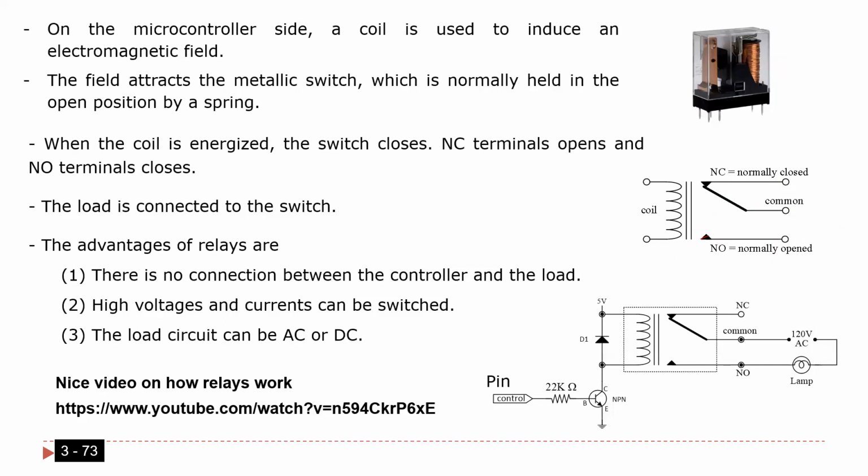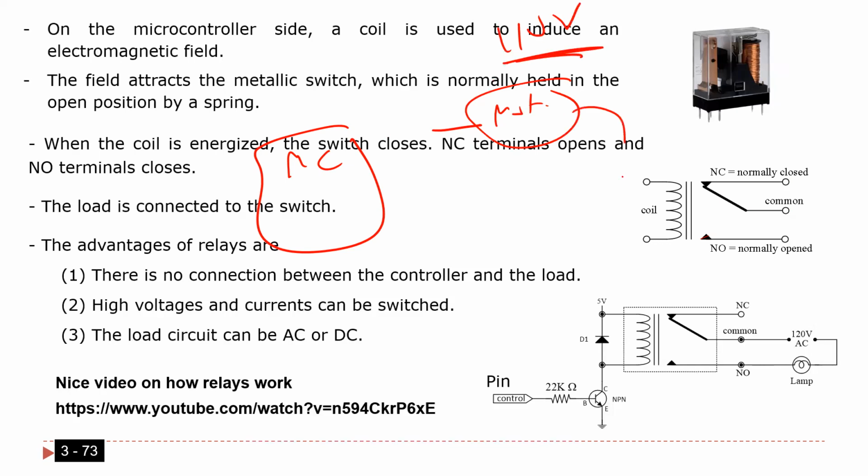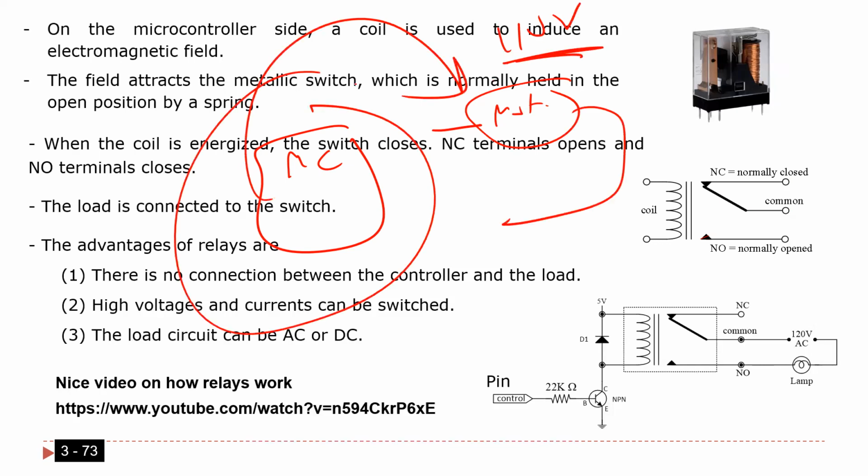Yes, that's what's called the relay. How is this interesting? You can use a relay to control a circuit with 100 volts, as you see here. I'm going to tell you how, using the microcontroller. Again, this is the problem we are trying to solve. I have a microcontroller. I have a motor, and this motor is 110 volts, and I want the microcontroller to control it: connect, disconnect, connect, disconnect.